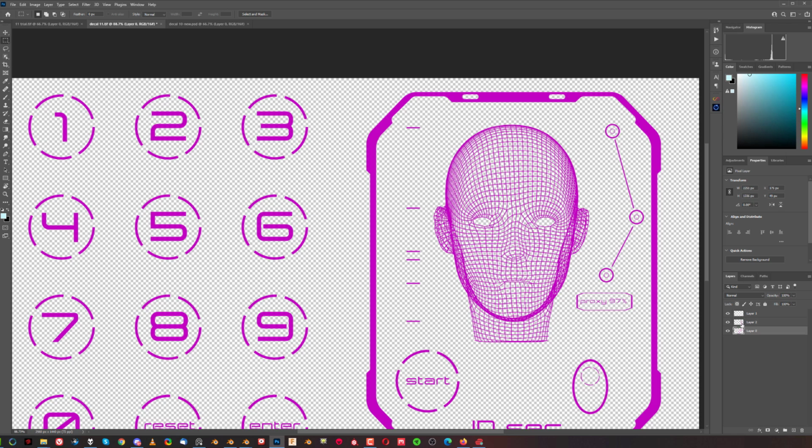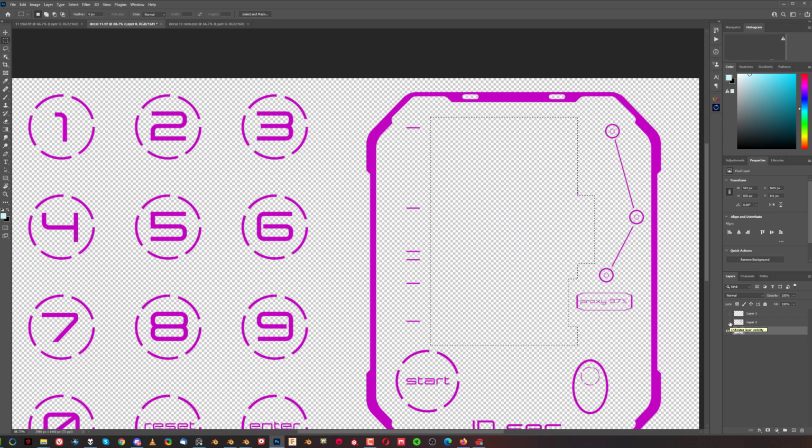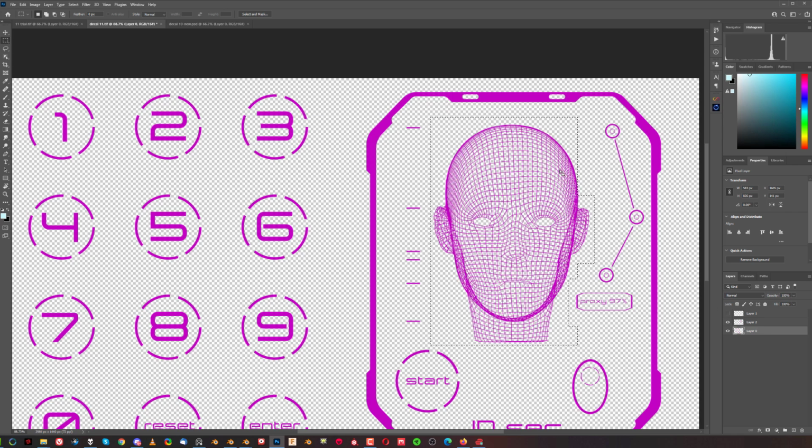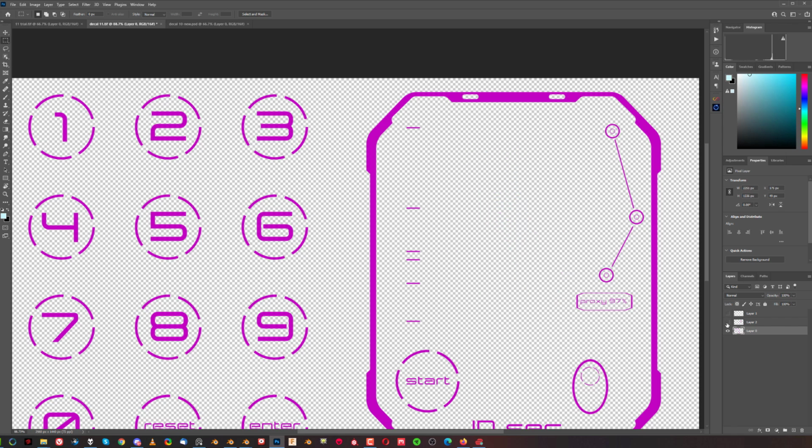In order to delete it, I'm going to turn that top layer off, and simply one more time select this bit here, hold Shift, select this bit here, hold Alt and deselect this one. And this should do, and just press delete, and this should kind of work. And no, it didn't. I need to also select this one and then press delete. There you go. Control D and this should disappear.